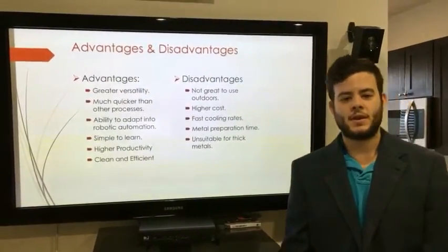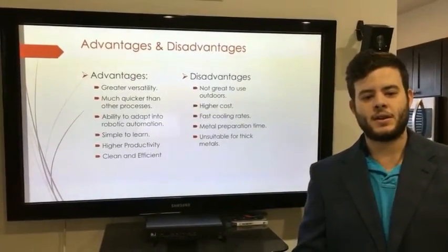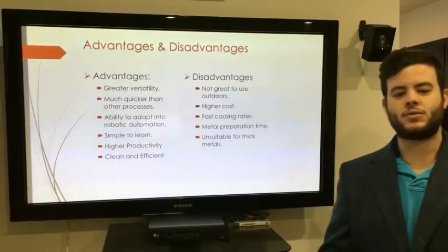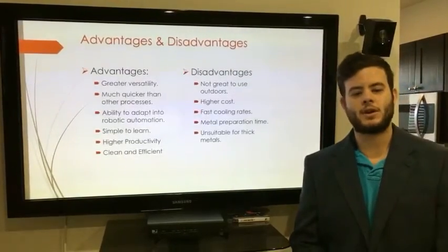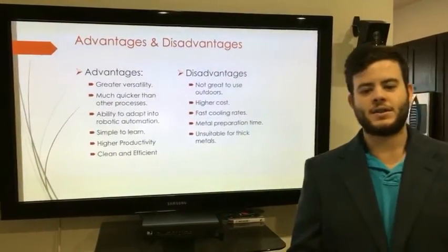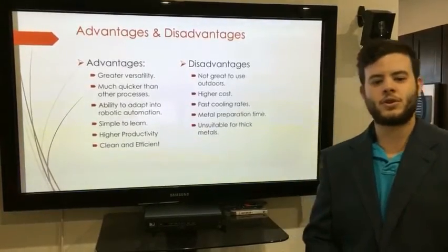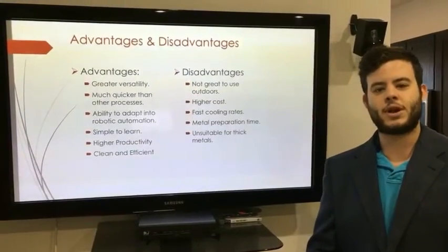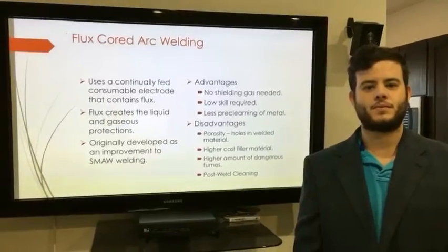Advantages and disadvantages. Some of the advantages are great versatility, much quicker than other processes, ability to adapt into robotic automation, simple to learn, high productivity, clean and efficient. And disadvantages, we have not great to use outdoors, high cost, fast cooling rate, metal preparation time, and unsuitable for thick metals.